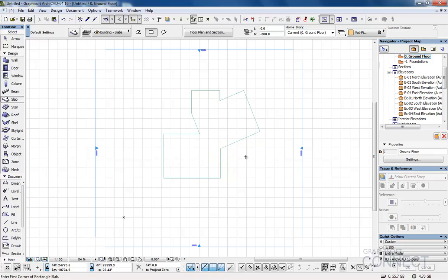And even at this stage, although this is 2D, there are already other settings behind it. So what I want to do is have a look at 3D, and we can look at navigation in there. The most effective way to get to 3D, personally, that I find, rather than using buttons, shortcuts, views, etc., is just to press a key on the keyboard. And the key you would expect to be F3, but actually on a Mac it's F4 and on a PC it's F5. This gives us additional settings which are more useful than F3.